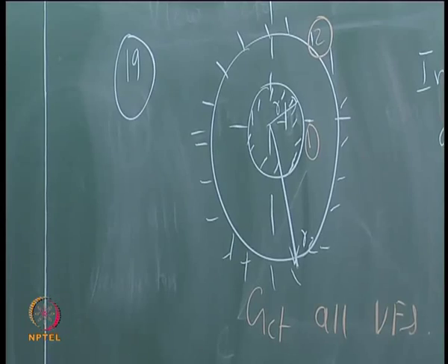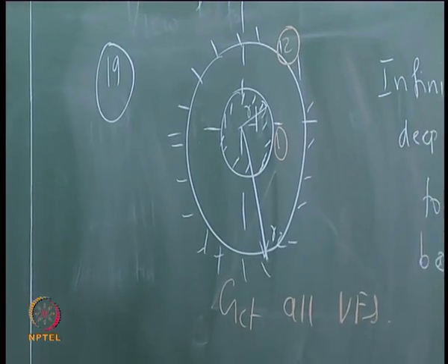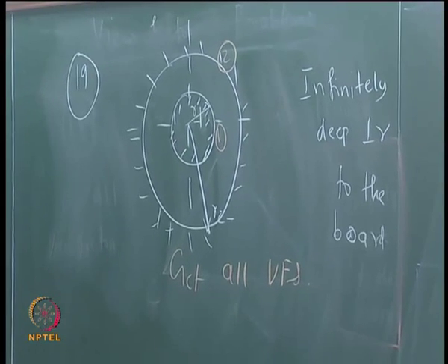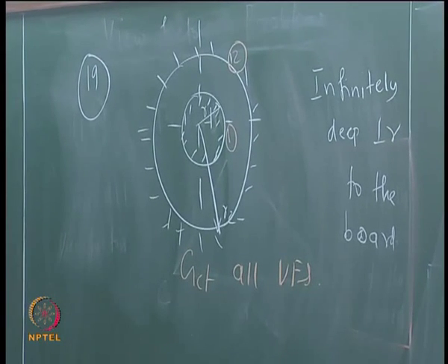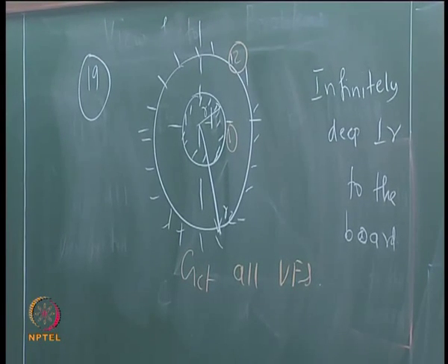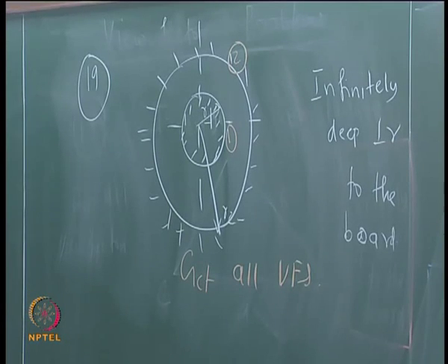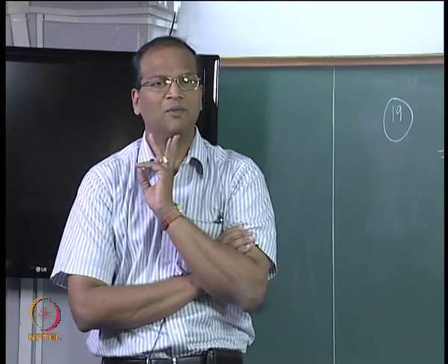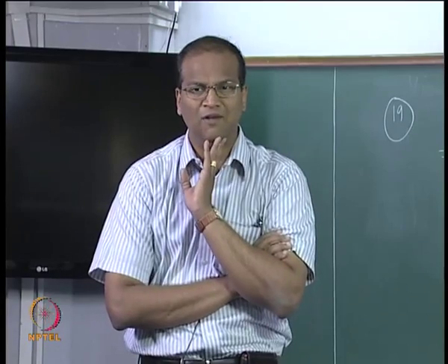This is one way of insulation. You can either have a flowing fluid or sphere within a sphere. It can be used for transporting liquid nitrogen, liquid oxygen and all that. When they transport it over large distances, the temperatures will be 150 or 160 Kelvin.